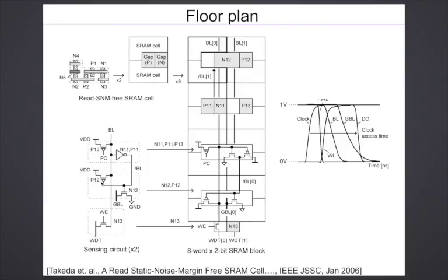Especially in deep submicron, it is a problem at high voltages, and that is why people have largely moved away from these dynamic circuits in deep submicron, because process variations make it very difficult to design your pull-up and pull-down, because it's like ratioing, right? You have to get the sizes correct and it has to work across all process variations. And it will become even more problematic in the sub-threshold.